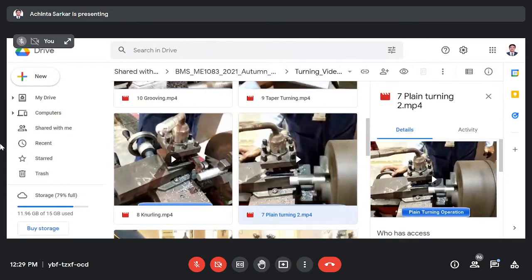Here in the lathe case, the workpiece is rotating, but it is not changing its position in terms of its axis, and the cutting tool is taking linear movement. So we can say there is relative motion between these two members, so we are able to cut the material. Machining or material removal processes are based on this principle, we have to establish relative motion between the workpiece and the cutting tool.